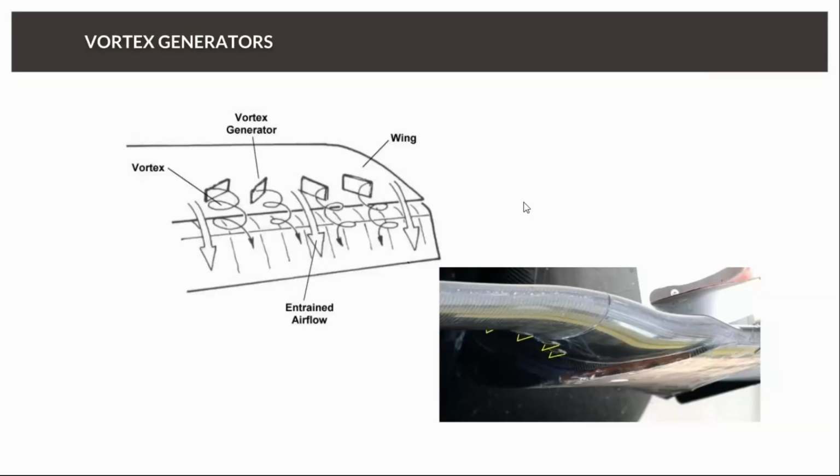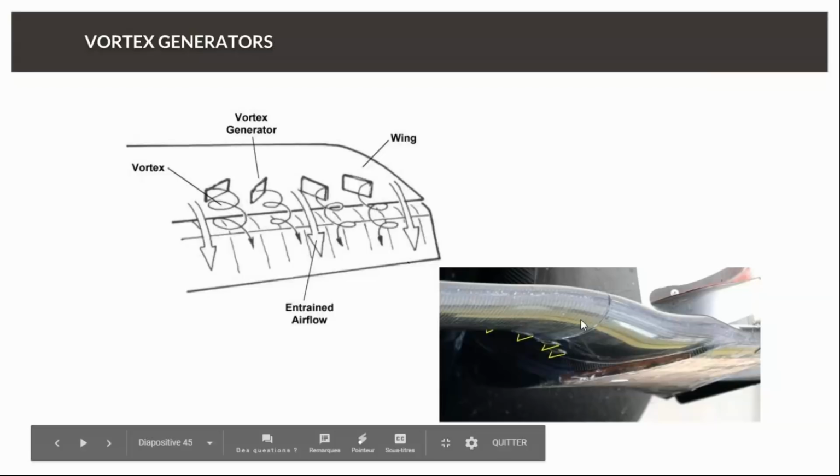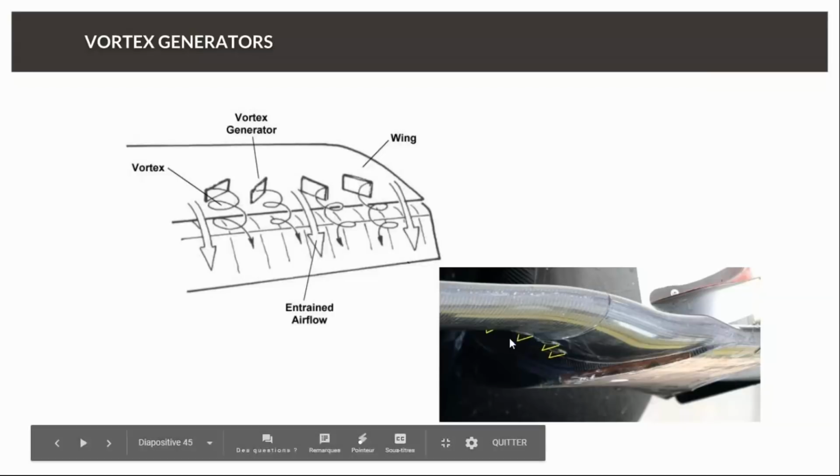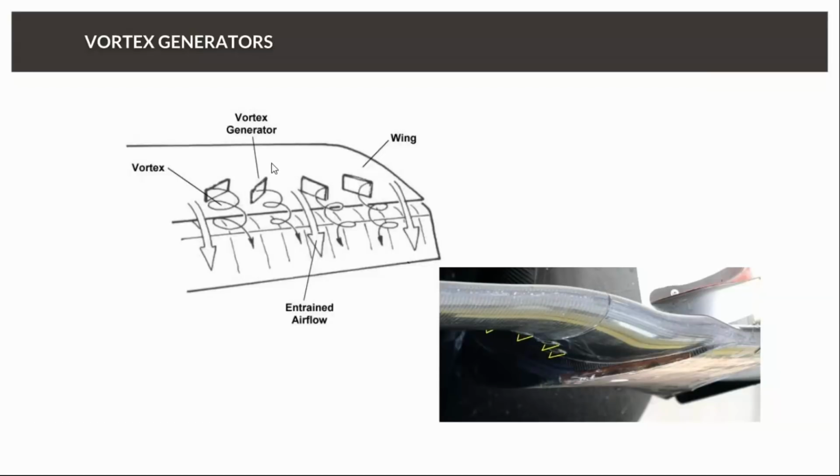And finally, a word on vortex generators. They're often used on splitters. Here's a picture of the Porsche in the WEC, World Endurance. Behind the main plane, the flaps are quite steep, and so sometimes, like on airplanes as well, in front of the flaps it helps to create some disturbances to give energy to the flow and help it stay better attached on very steep surfaces where the pressure gradients are high, so where the boundary layer is at risk, and there the little vortex generators will help to keep the flow attached, and so you can use your geometry to create more downforce.